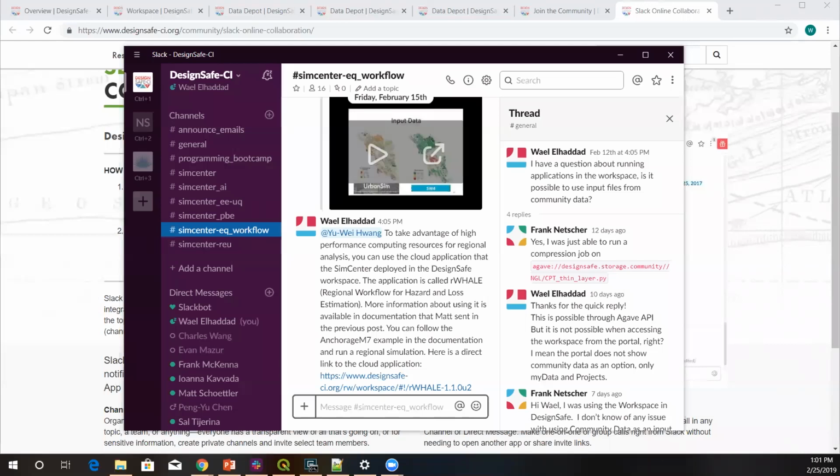The way it's done is it's based on the design code forces, basically. So the model is still based on HAZUS to some extent. The only difference between this and using a capacity curve in HAZUS is that this model is expanded to be a multi-degree-of-freedom model, so it will give you response at different floors.